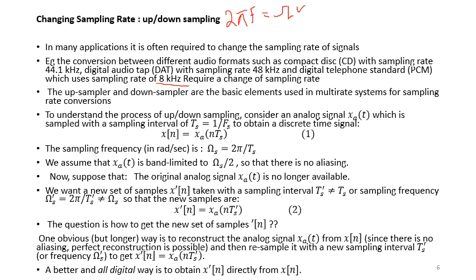So in case of linear frequency, the maximum frequency, for example, we have Fn. So 2 times Fn should be, by the Nyquist criteria, the sampling frequency, let it be represented by Fs. So Fs should be equal to or greater than 2 times this one, right? So that's in terms of the linear frequency.